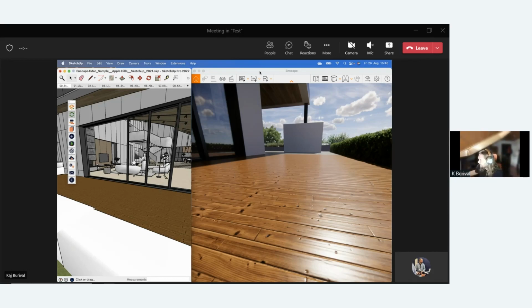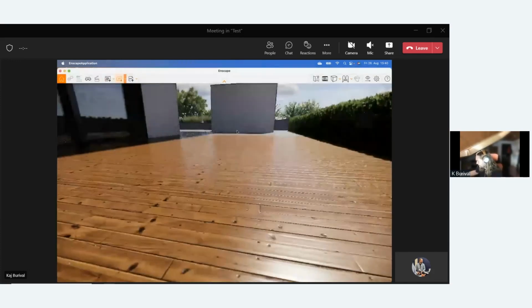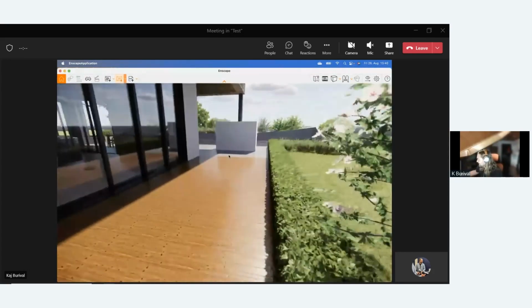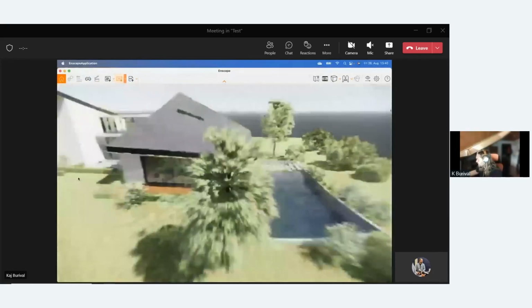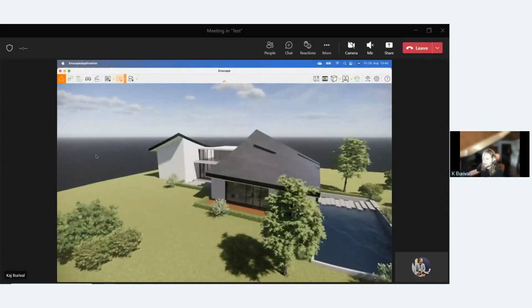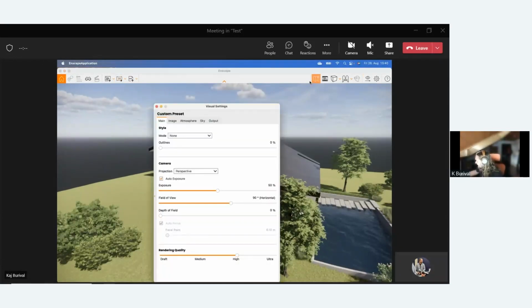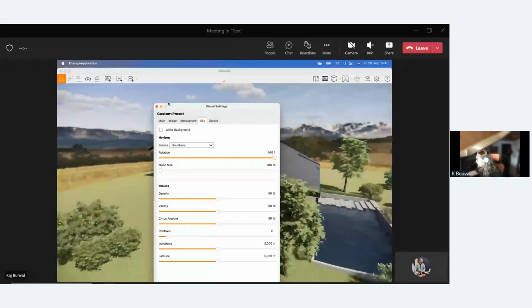All right, that is a little bit of the toolbar on the SketchUp side. Let's have a look at what you can do on the Enscape side as well. And maybe as a first step, let me dive a little bit into the visual settings, because I don't like this environment, this black void we have there. So I'm going to click up here, the visual settings, and change the sky. There should be a skybox displayed, but I think it's not linked on my machine. So I'm just going to use one of our horizons that we have.